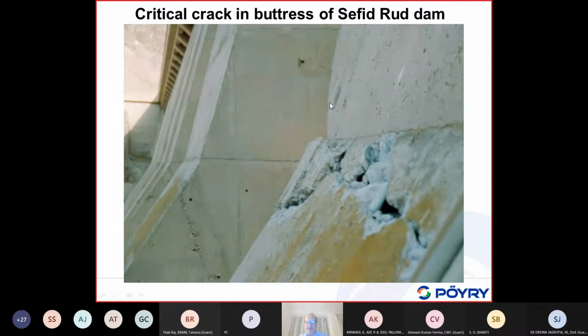And I mentioned it already previously in a discussion of stress concentration. It is clear that if you have a sudden change in slope, you have a kink here. If it were theoretically a sharp kink, the stresses here very locally would be infinite.